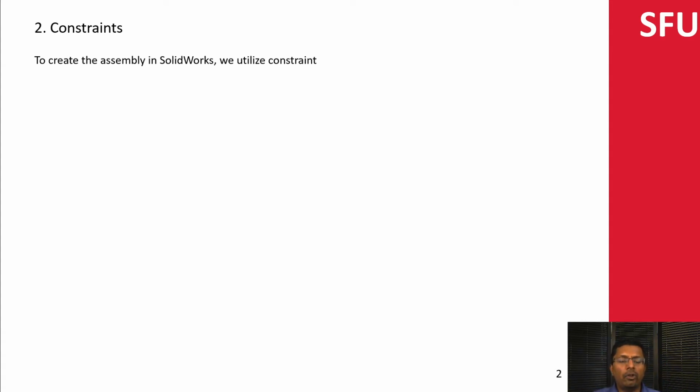Unfortunately, that is a lot of logic to actually program into SolidWorks, so it doesn't really know concepts of gravity, or you can set it up, but it just makes the whole calculation a lot more difficult. And then you can talk about the clearances, whether or not it's going to fall out. You can program all of those together, but that would make the program very, very complicated, and it doesn't really give you too much of a benefit. More often than not, it could mess up and you wouldn't be able to create what you need. So instead, we impose the effects of the constraints within SolidWorks.